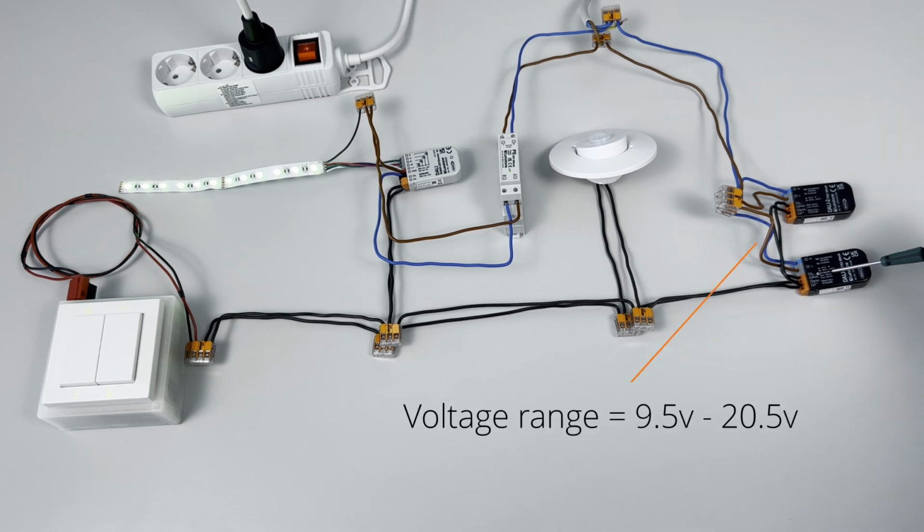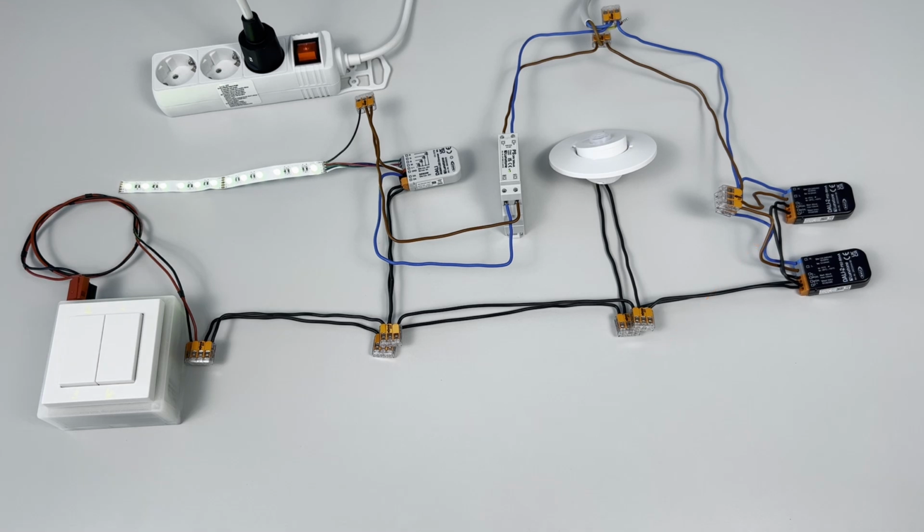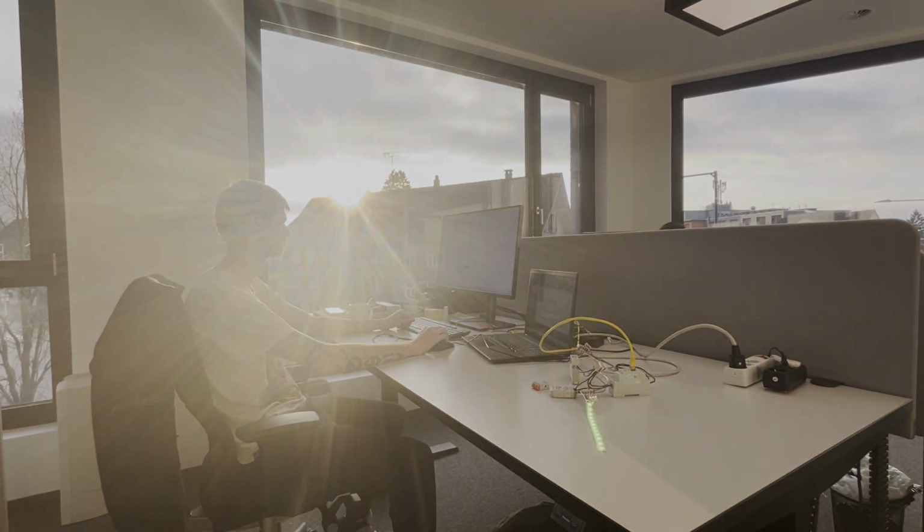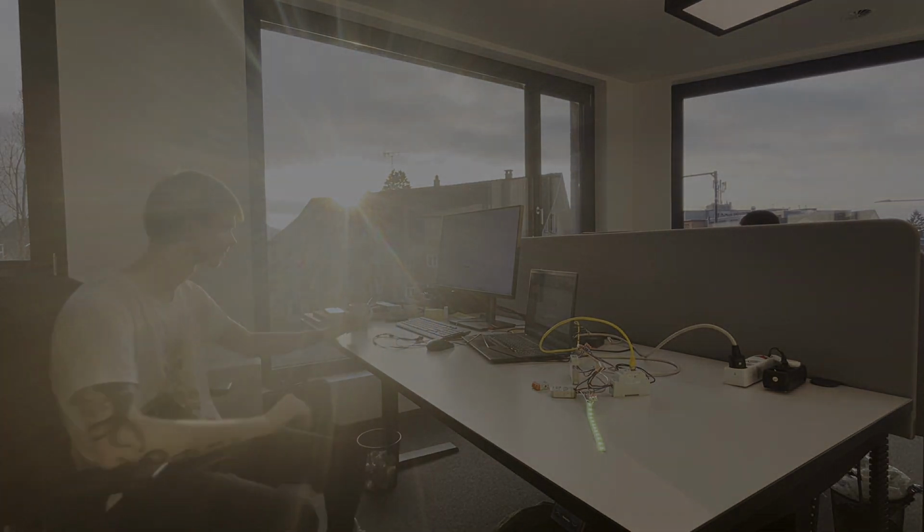Measure the DALI power supply output. Voltages should be within the DALI range of 9.5 to 20.5 volts. Current must not exceed 250 milliamps. Now that we've covered the theory, practical examples, and common power issues, you should be equipped to correctly power your DALI system using Lunatone devices.